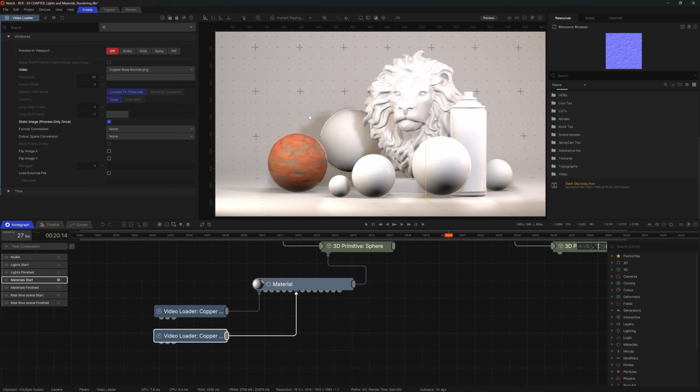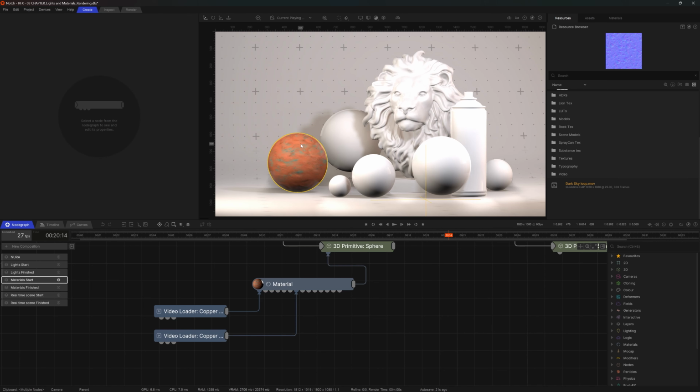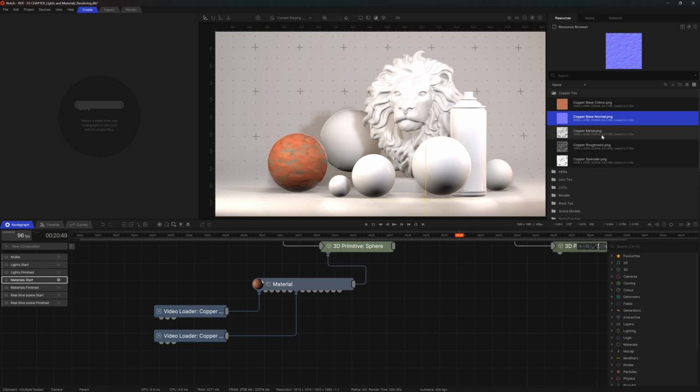So what does the normal map do? Well, it actually emulates or gives this impression of depth. So you see there's already these little dents and imperfections appearing as soon as I add the normal map. Very, very handy way to add details to your model without introducing extra cost of, let's say, displacing the geometry and adding subdivisions.